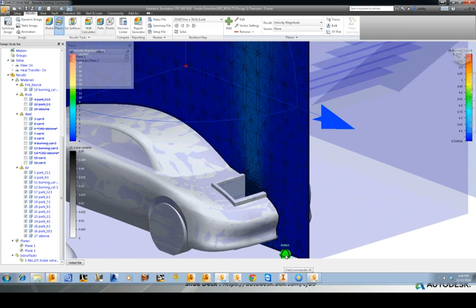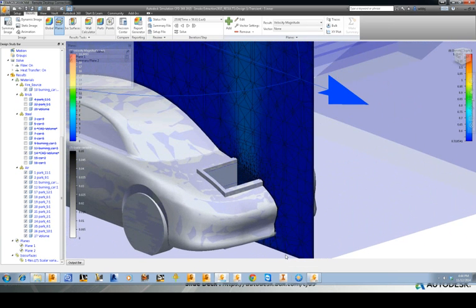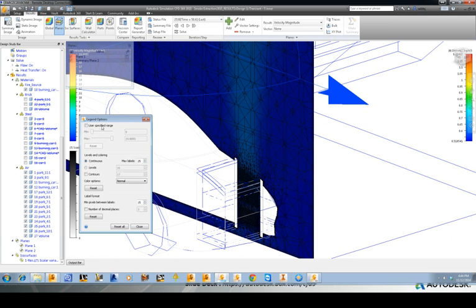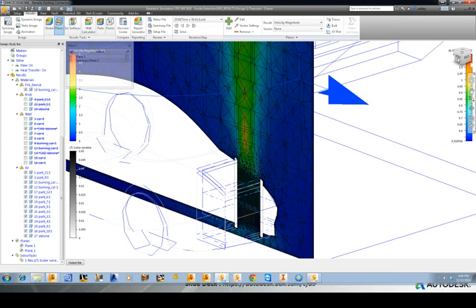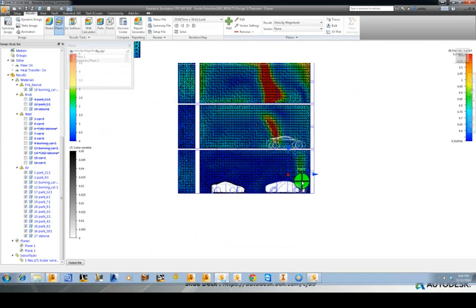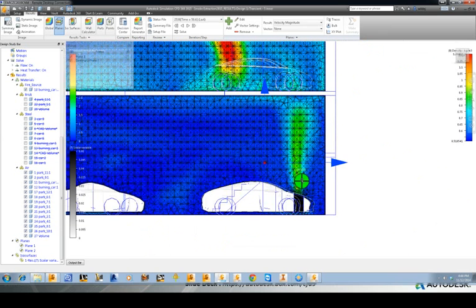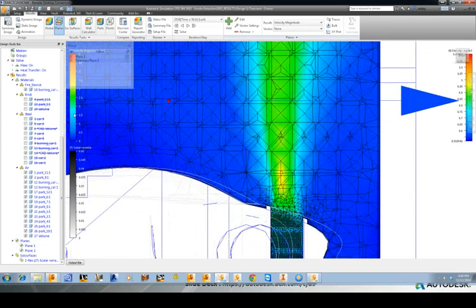There are a couple of key points to look for when you have these defined plumes. If the plume ends up following the mesh edges very much, so if we were to take a side view of this, John, and look at the contours along the outside, if that plume started to follow those edges, that'd be one key signature that you definitely don't have enough mesh there, because the flow is actually following the edges of the elements. So that'd be step one.